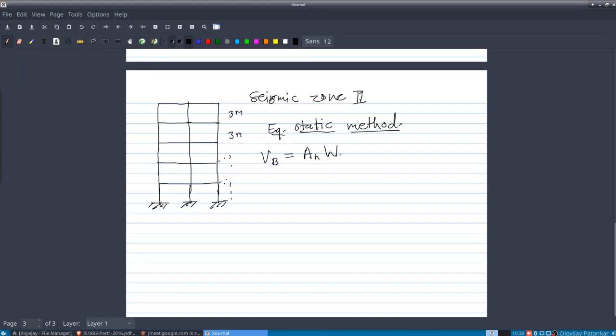There will be many details that I have to provide, but let's not get into those calculations actually, because those calculations are very simple. You can very easily find out how to do all these calculations. To calculate seismic weight, it will be just like unit weight of concrete or RCC, that is 2400 kg per meter cube, and then multiply that by its volume.